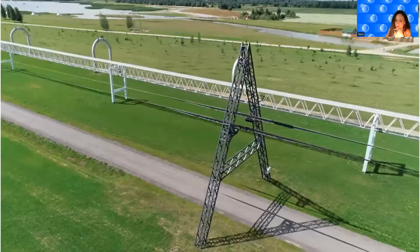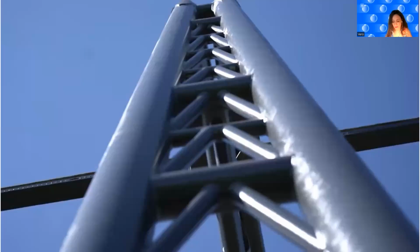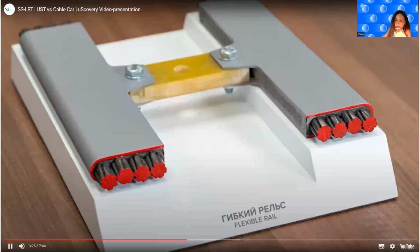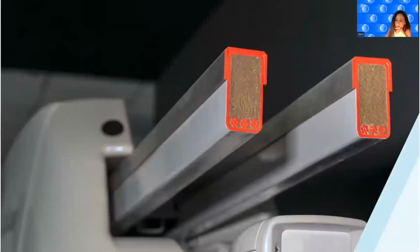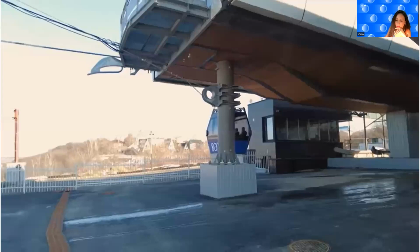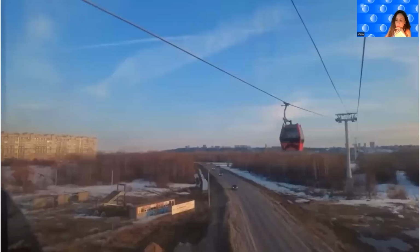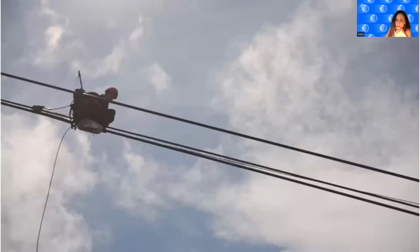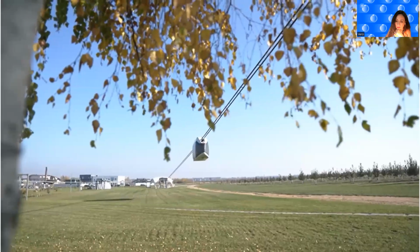The load-bearing string elements of the transport overpass have a tenfold margin of strength. They are resistant to vandalism and terrorist acts. The rail consists of steel reinforcement elements fitted in the core, a filler, and a high-strength housing, which increases its overall strength. As a track structure, cableways use only an ordinary twisted rope that is unprotected from mechanical and climate impacts. Cables of most systems known in the world need to be completely replaced with a frequency of 3 to 10 years. The service life of the UST String Technologies track structure is at least 50 years.